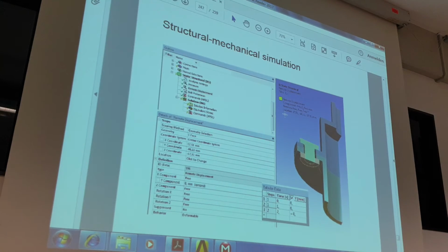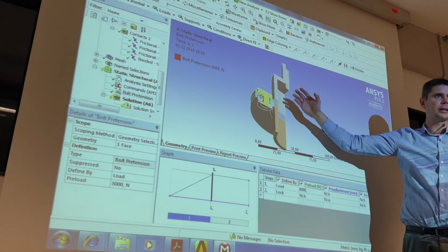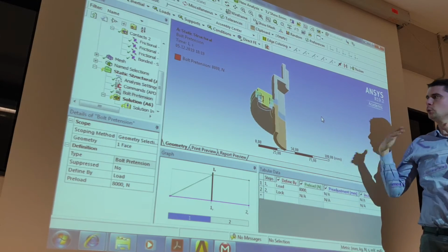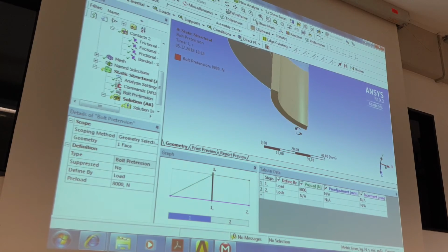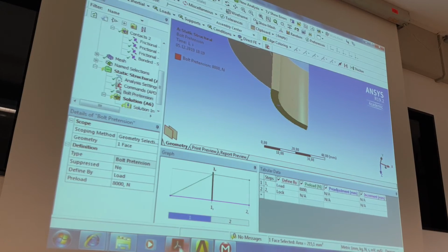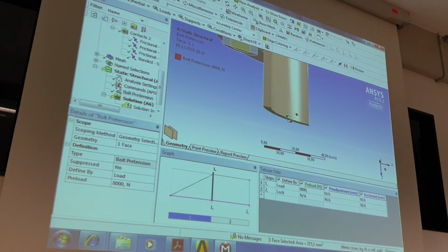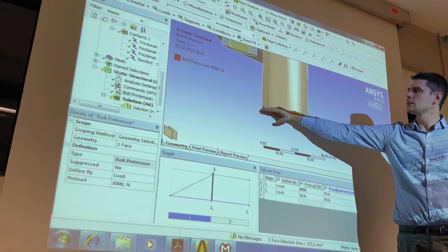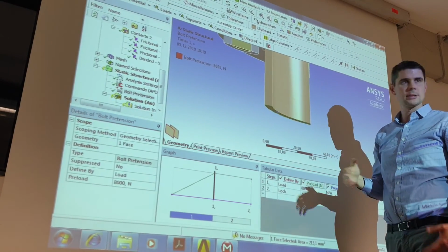Second step is pressure. Okay, of course we need to fix something, yes? So, okay, if I do now pressure, then after simulation starts, my parts move far away, yes? So I need to fix something, yes? This is a tube connection, and normally I can say without problem this face not fixed, but this place is, for example, in my axial direction fixed, yes? So this is tube. It means it's going to go outside, yes? But I always have here one tube, yes? If tube long, I have always this tube in this place, yes? I can say something I have to fix, yes?